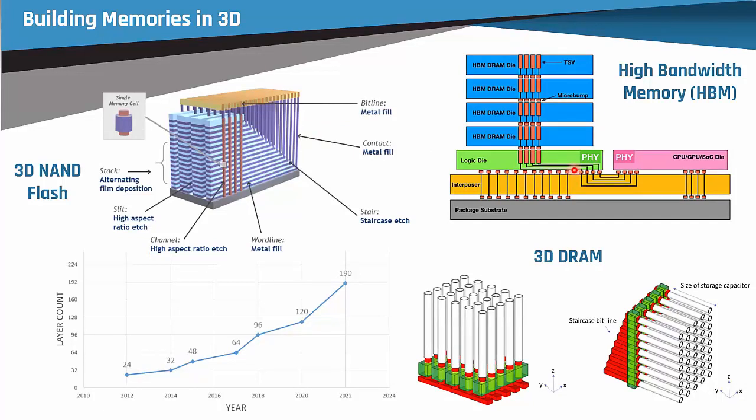The other thing that you have is high bandwidth memory, HBM, which you find inside GPUs and so forth, which is a way to get more DRAM on your chip. And this uses this 2.5D on one side where you have the GPU or CPU or something on the same shared interconnect substrate as your memory, but then the memory is stacked on top of each other. And again, they use this fact that the DRAM chips are exactly the same and they can make them so you can stack them, and they have 8 or maybe even 16 now dies of DRAM stacked on top of each other, so you can get a lot of memory really close to your processor. But that's only semi 3D.